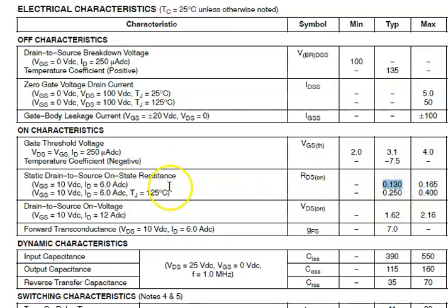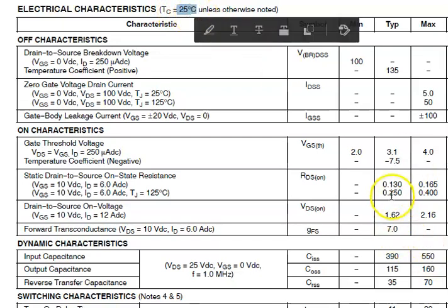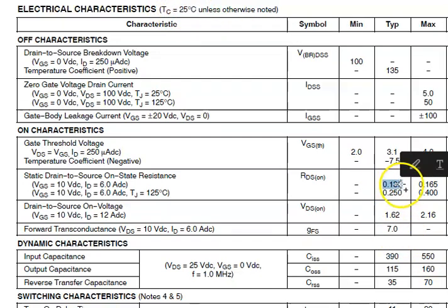So 0.13 is another value which indicates certain values of junction temperature, but this is the value of the initial condition at 25 degrees C. Later at other temperatures, we shall use the normalized factor to multiply by a ratio to get the values at that temperature range.